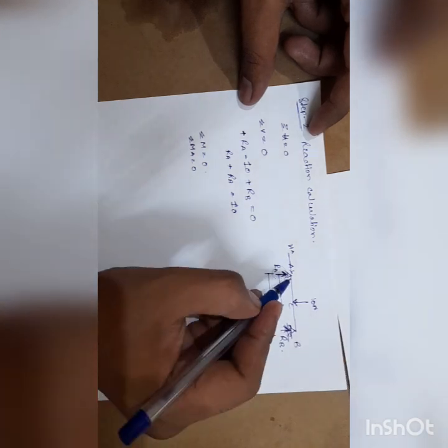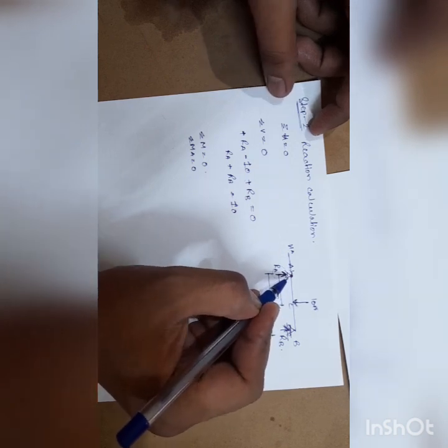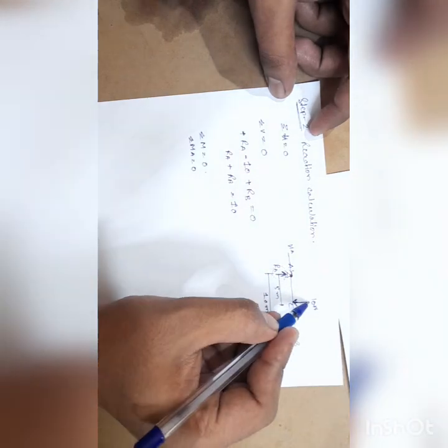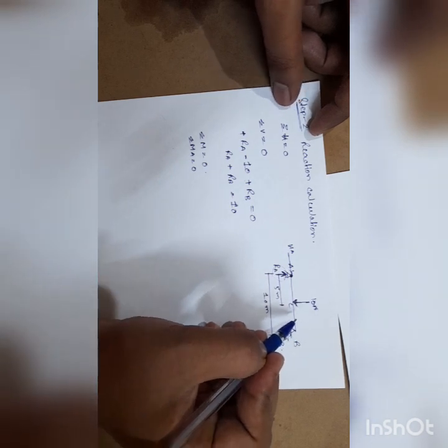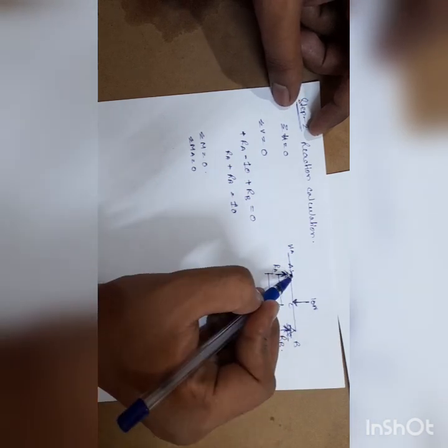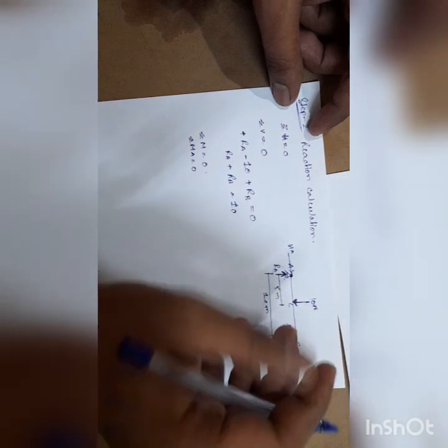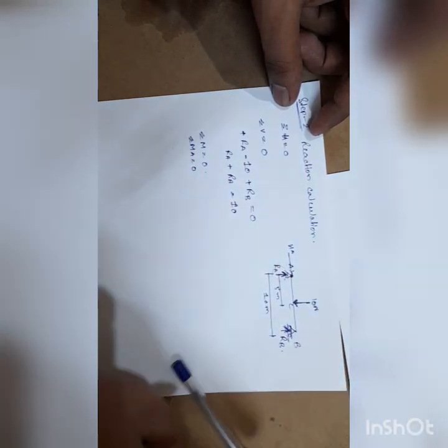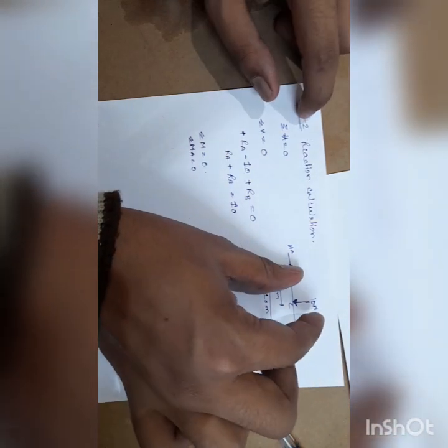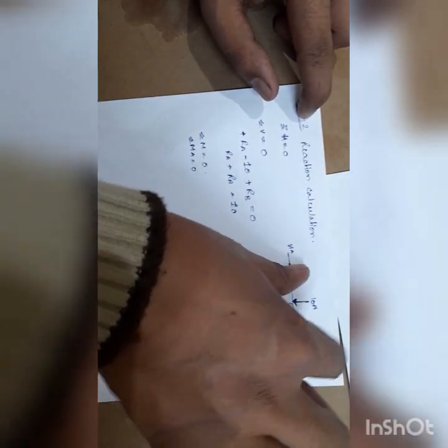Now if we are standing at point A, which force can give moment about that point? First is the 10 Newton. What is moment? Force into its perpendicular distance from that point. So from point A, this 10 Newton is acting in downward direction. Take your hand like a compass: one point at the point from which you are taking the moment, and one point in the direction in which the force is acting, and rotate it.